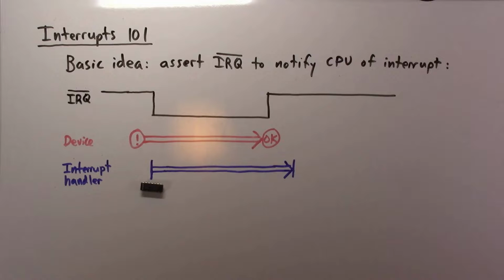memory buffer. It is important that the interrupt routine completely resolve the situation that triggered the interrupt so that the hardware device deasserts the CPU's IRQ input. Otherwise, the interrupt handler routine will be executed over and over again. Once the interrupt routine has resolved the condition which generated the interrupt, the hardware device will deassert the IRQ signal. The interrupt handler will return once it is completed. Assuming that IRQ has been deasserted, normal execution will resume.